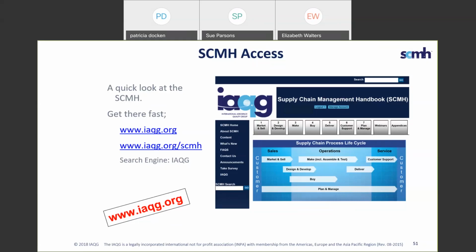What about using first article unique identifiers, AS9102, as the characteristic IDs? That's certainly an option, and particularly if that was also used as an ID in some of the other artifacts like the process flow and PFMEA, so that you'd have that linkage. That absolutely could be something that you could do.